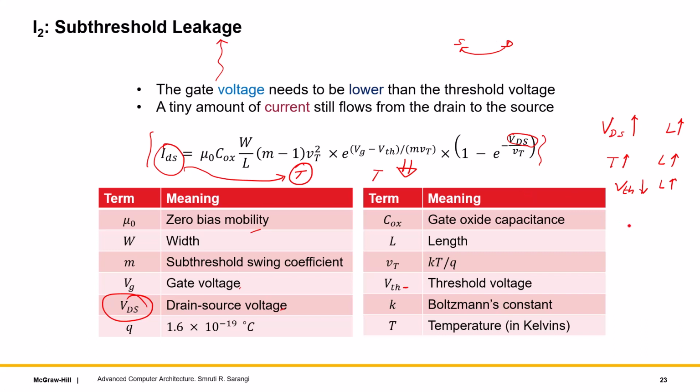See, here again there is an interesting leakage temperature feedback loop, because as the leakage increases, the power increases, which means the temperature increases, which means the leakage increases. So if this is a converging series, it's fine, but if the series is divergent, then it's a fatal case, right, for the processor. It's known as thermal runaway. So we will discuss this later in a subsequent slide, but broadly speaking, this is where we are.